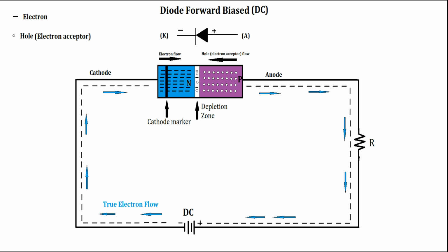On the purple side, we have silicon doped with semiconductor materials such as aluminum, boron, and gallium, which allows for there to be more electron acceptors, or holes. This is P-type material. Doing this allows the desired control of the flow of current through the diode.